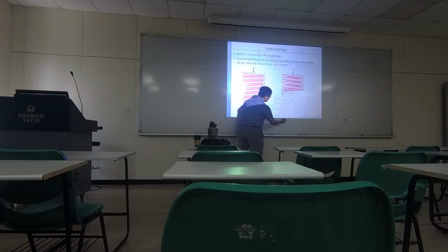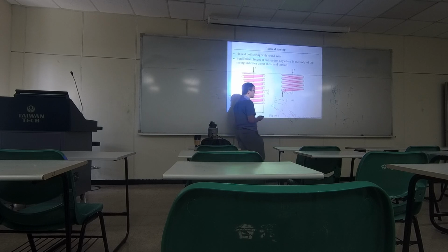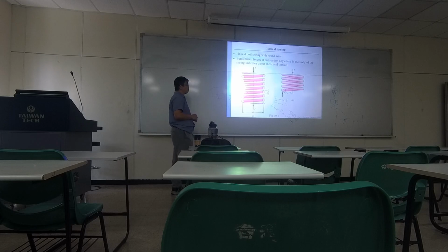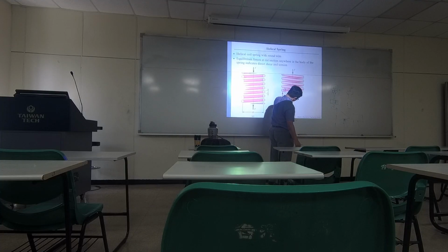So this part, the torsion part, comes with a correction factor, like a coefficient. Okay, coefficient, and it's been experimented and realized how much correction is needed. So you can then compute the more accurate shearing stress inside the spring. If you know the stress, then you can make sure it's within the safety range. Okay? So in this particular lecture,